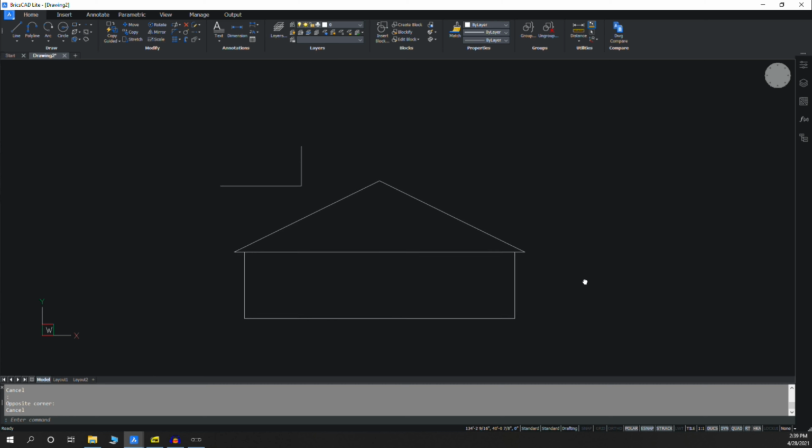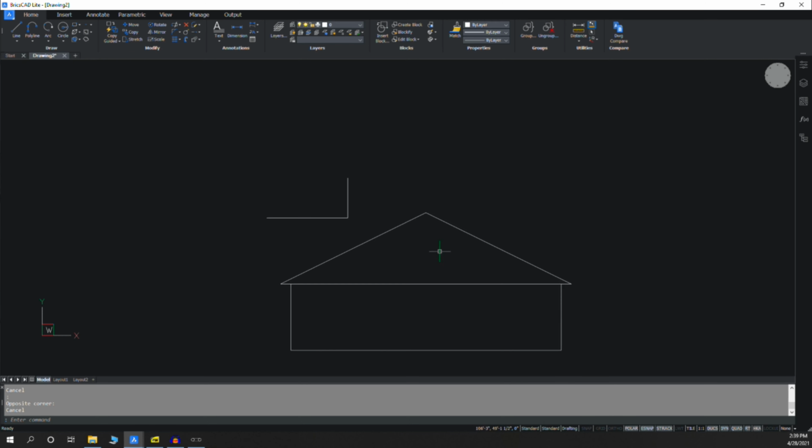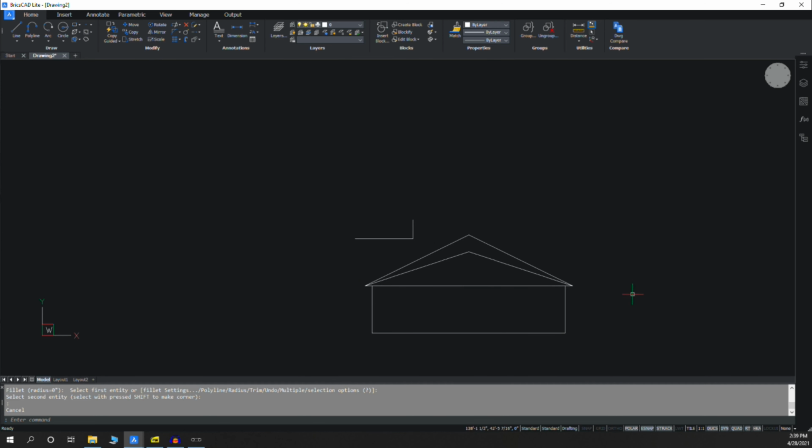So that's cool, but maybe I don't want a 6-12 roof. Maybe I want to see what a 4-12 looks like. In a lot of cases, I'll just draw that directly over what I've got. I can delete the line we used to make the 6-12 pitch, and instead of going up 6 feet, I'll go up 4 feet. So now I'm going over 12 feet, up 4 feet, and if I draw a line here, I have a 4-12 pitch. I can grab that, move it, and snap it to the same place. I do my trick with the mirroring again, and then filleting to get the roof in. Now I've got the outline of a 6-12 pitch, and the outline of a 4-12 pitch.